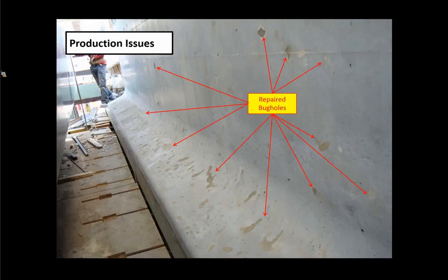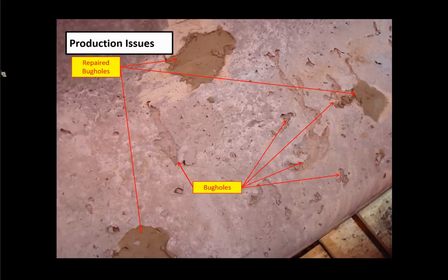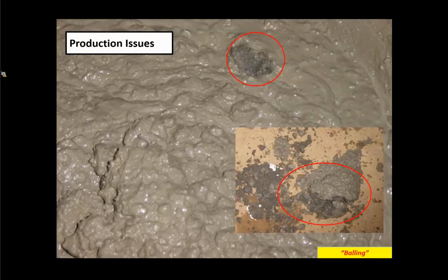So in that case, you see that the main issue they were having is a lot of bug holes in the bottoms of those girders. Obviously you can think about, well, were they vibrating things well and all that? Sure, the contractor at that time was doing all the efforts that he could with that mix, but the mix was still not responding well to that vibration effort, right? You still could see how the mix was, to some extent, very sticky, right? You can see that in those surface areas the mix shows up as a big bug hole, but you can call it something else, because it's bigger than just a bug hole. But you can see the challenges that they were having there with the finished surface. And some of the things that were obviously observed as we started getting involved is that there were some issues with the material mixing, right?